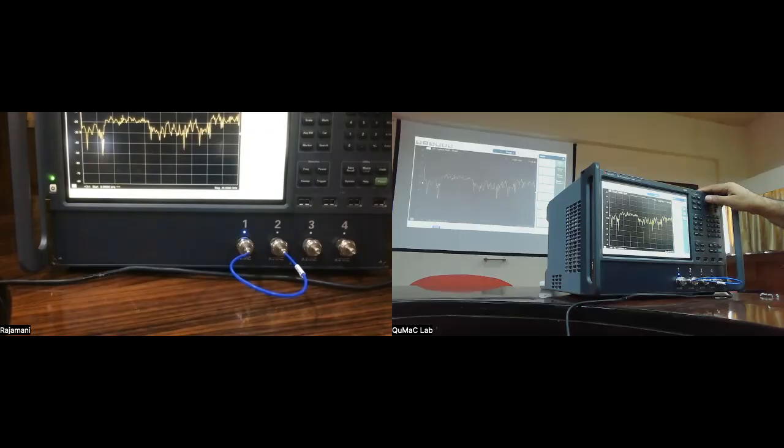Again, this is slightly unexpected behavior. Maybe this instrument is also not in its most optimal state, but this is quite reasonable. Because then it comes back again down to this -30 level and stays there most of the way. And then even all the way up to 20 gigahertz, you have something like -20, -18. So which means that this is only reflecting at the most 1% or a couple of percent of power. So that cannot explain the 1.5 dB of power we saw less coming into the other port. So that is basically due to the losses in the medium.